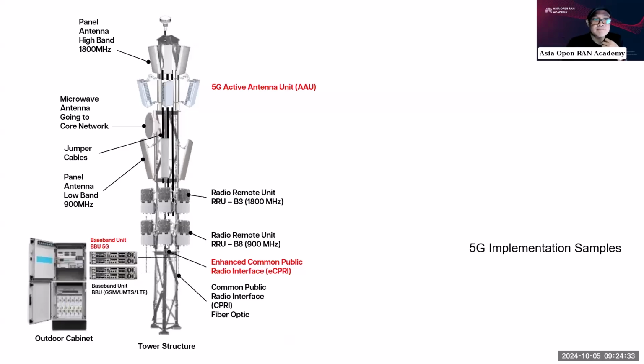So ito yung ating 5G, and then may makikita kayo sa taas na bagong element. This is what we call the GPS for synchronization. Especially if you are using a TDD, a time division duplex system, which needs careful or critical synchronization. Okay, kinakailangan synchronization. If not sync sa ibang site, it will cause interference because you are using only one frequency in the downlink and uplink. Okay, so you need the GPS to do the synchronization.